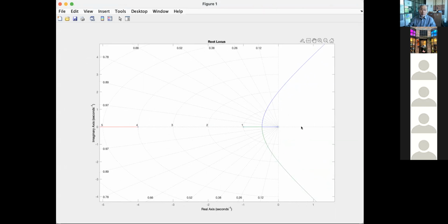So what information do we want to find here? First, if the question asks you to give a few comments on the plot, just say that the root locus has 3 paths, which are shown here: the yellow one, the green one, and the red one. Why 3 root locus paths? Due to the 3 open loop poles, which are S equal to 0, -1, and -4. That is comment number 1.